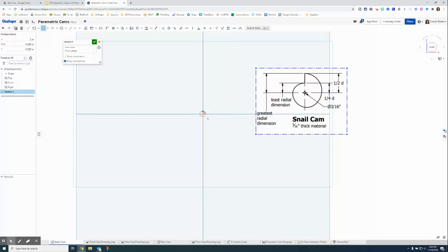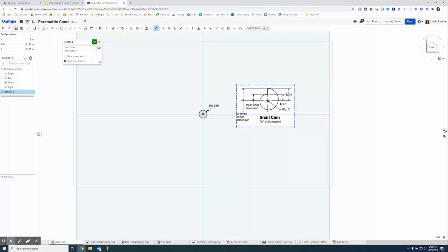So I'm C for circle, bring that hole out, D for diameter, click that circle, hashtag hole, and automatically it programmed into what my configuration is set up over here. If I wanted to change this to a 1/4 inch dowel rod, I can do that really quickly, but I'm going to keep that as my 3/16. There we go. All right, so 3/16.